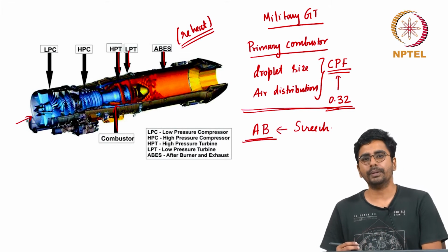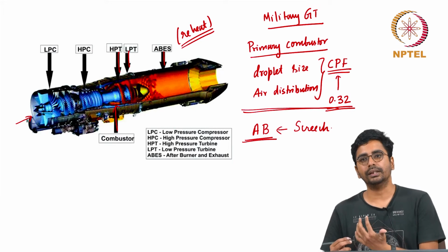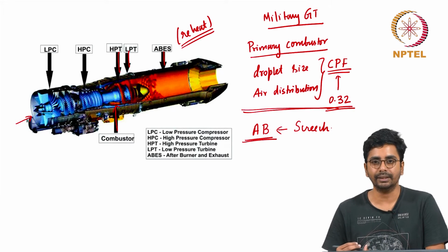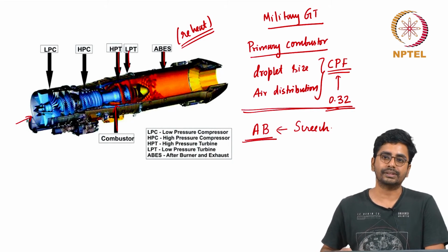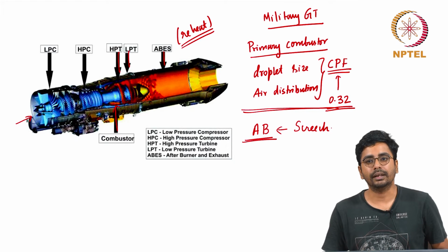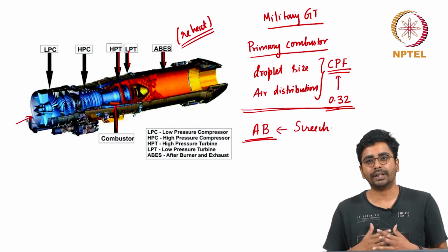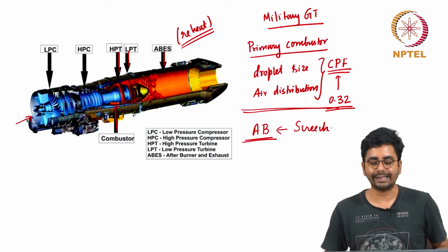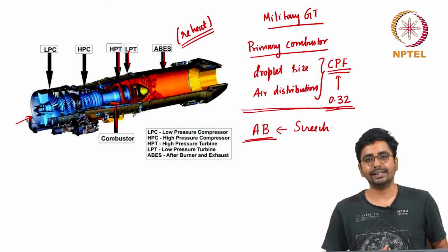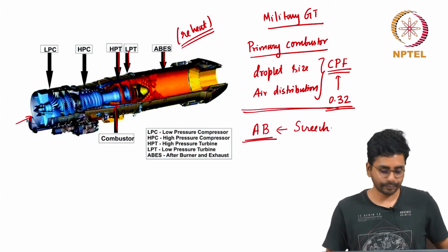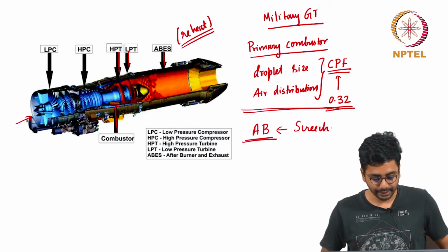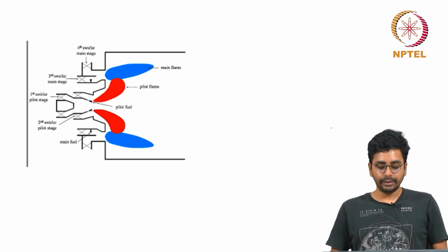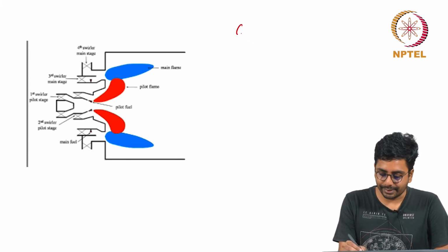The non-uniformity is predominantly created by the swirl of the flow that comes out of the turbine, and in some designs anti-swirl vanes are used to nullify the effect of the swirl, creating a more or less uniform stream of hot gases coming out of the turbine, and that seems to ensure stability, and that is the key idea here. Okay. The next is civilian aircraft.